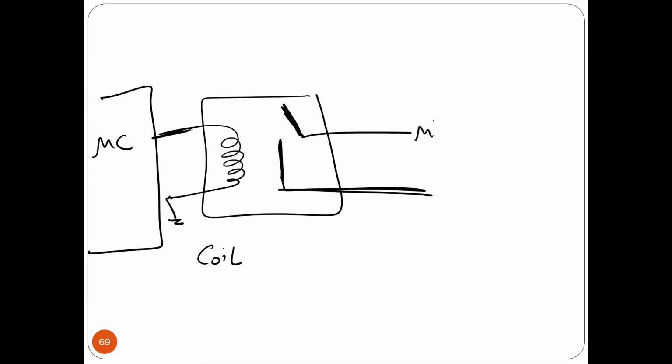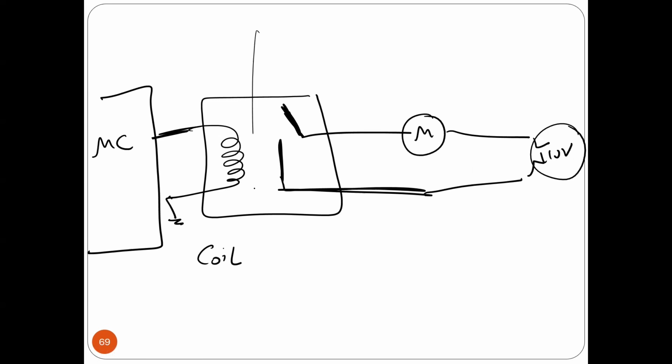And then I can connect the motor this way, and then I can put here 110 volts. Here there is air, so there is no electrical connection here. Okay. So how does it work? What is the main idea? Very simple. You connect it to just one pin. All you have to do is put 5 volts here, or put a logic 1 on this pin. Once you do that, you energize the coil, so the current goes this way.